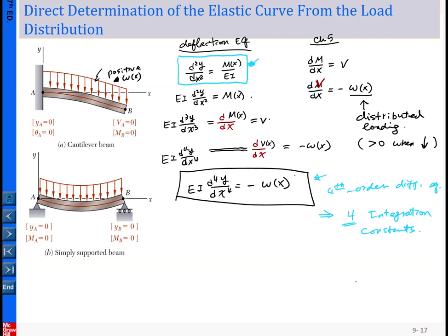Then the boundary conditions, you can in general split into 2 categories. Here we can see for the cantilever beam, at the support there is zero slope and zero displacement. So that is from the previous one we learned. On the other side, this is called the free end.